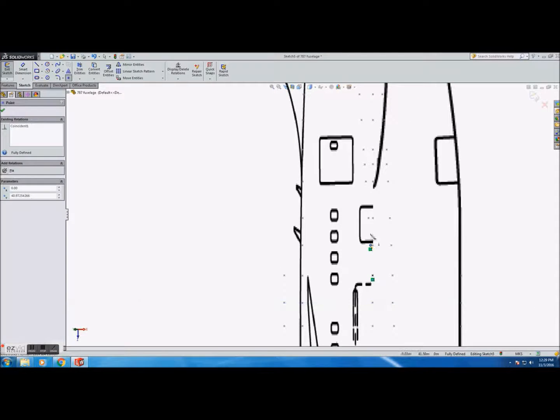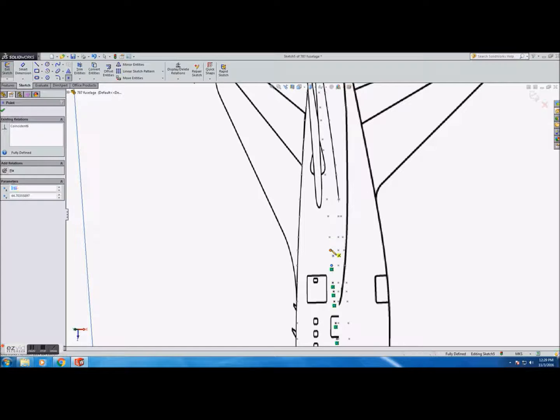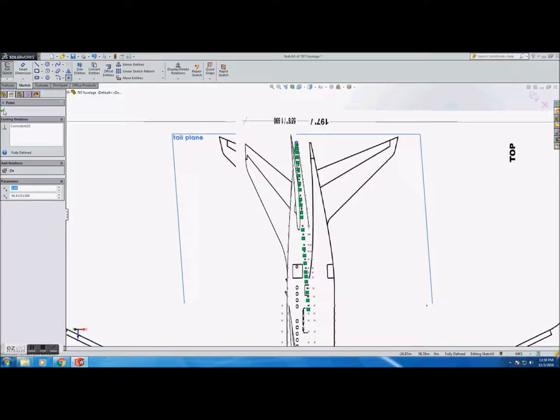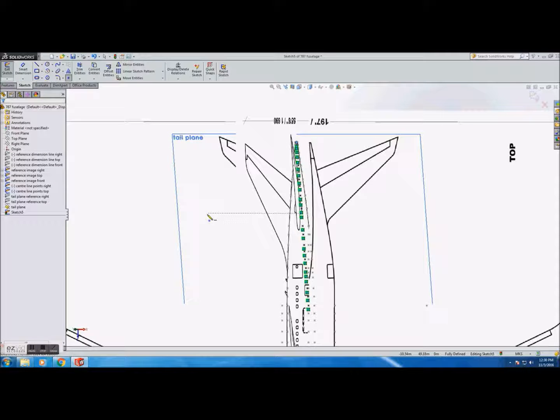Here I've just rotated the angle a little bit so that we're still within 45 degrees of the normal of the plane here, and we're still editing just this plane. If you go outside of 45 degrees, then obviously you're not going to be able to do anything with the points anymore, but we're going at this angle just so we know that we're clicking on the right points, as opposed to the ones that are on the center line.